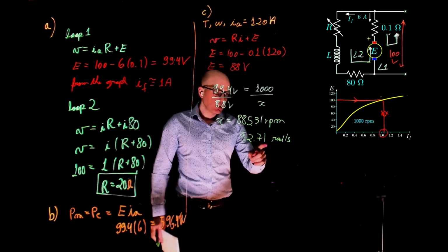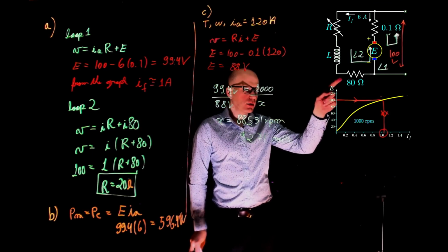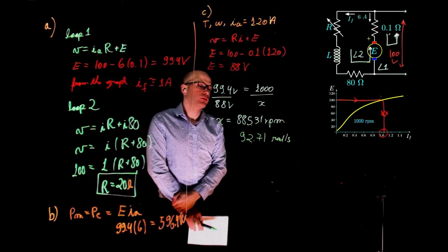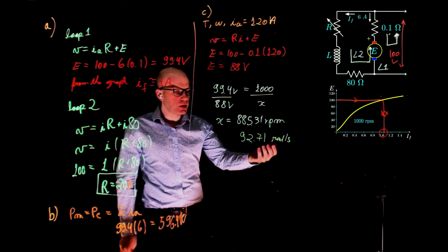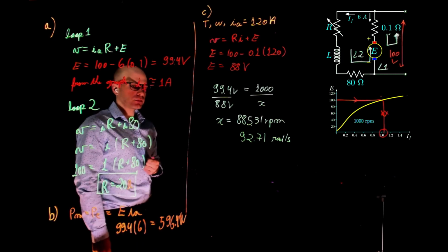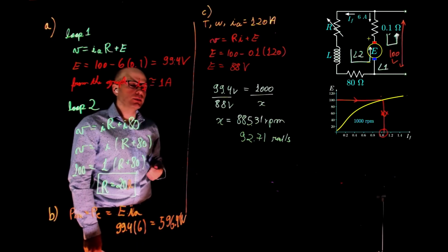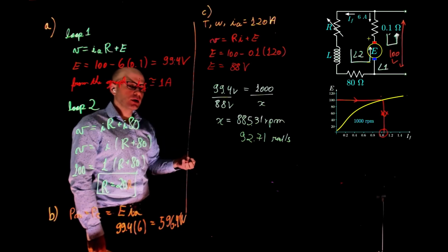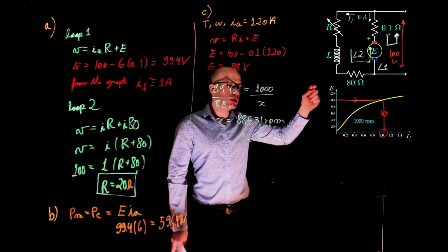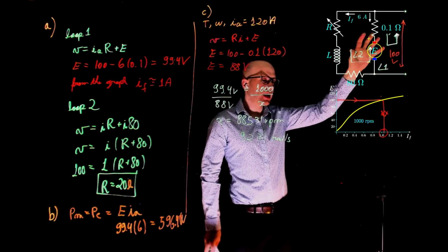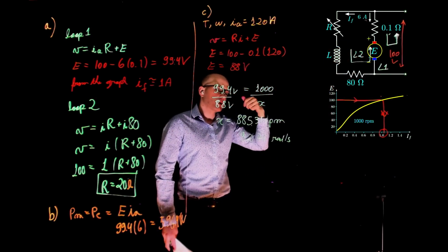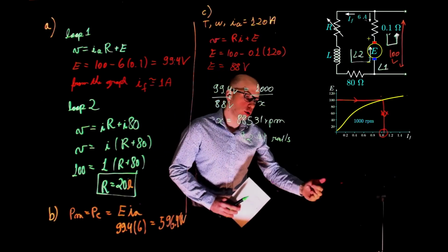Interesting. So the speed of the motor decreased and the current increased. What happened there? What would make the speed drop so much and the current increase so much? Torque. A torque, exactly. A load has been applied to the motor. The speed decreases, so this E also decreases, which means from the balance of forces there is less voltage being generated against this current. The current increases to supply the required torque that has been applied to the motor to lower the speed.